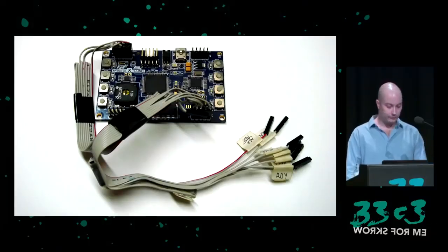Later on, when I did more thorough research, I did so using an ACP that I had removed from the box and put on a breakout board, and then I could control the clock. And at that point, it was much easier to use an XMega AVR platform to send and receive the transport stream through the ACP at a much slower bit rate. Shown here is the XMega platform I settled on using for SPI and also the transport stream interfacing.